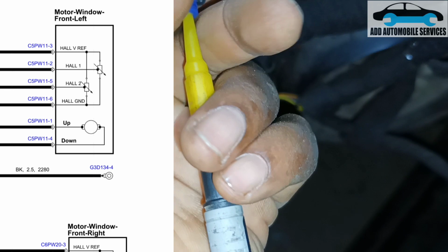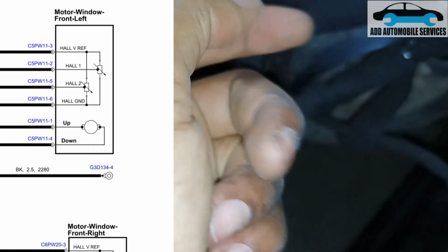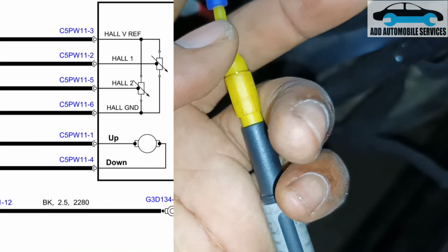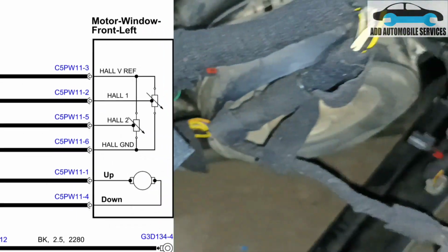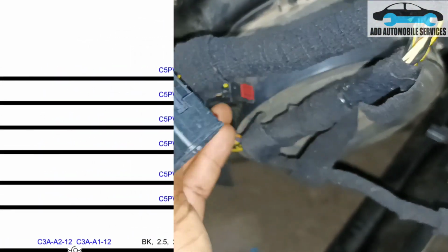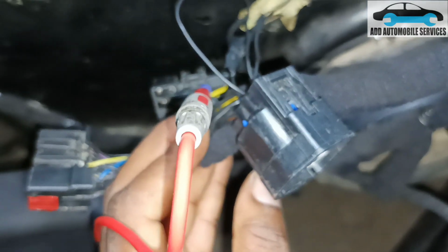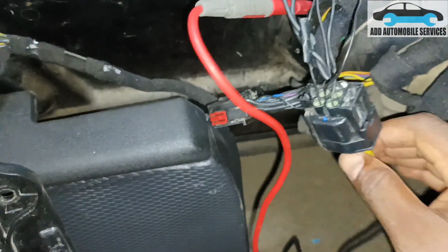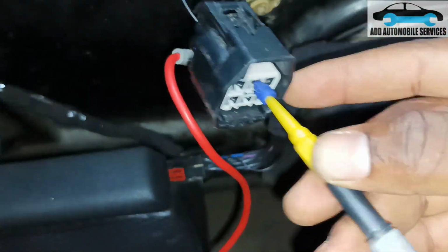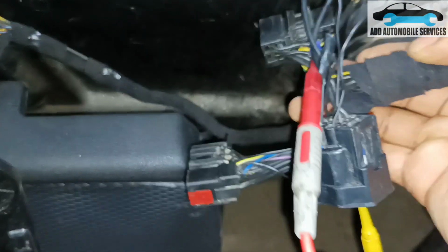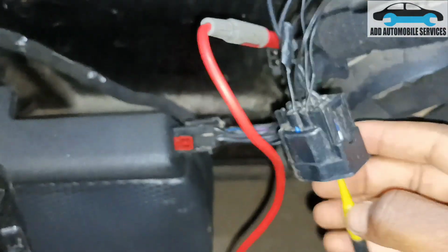So now let me move to the next pin, which is pin 2, and search for which connector it goes to. But for me doing that, I'll rather do it at this point. When I move to pin 8, that side, I can diagnose it and know the actual problem. With this one also, the pin is in pin 2, and this one is in pin 8, but it's not beeping.